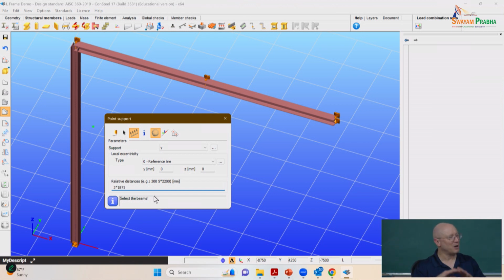Out of plane. Yeah, we've been talking about an in-plane analysis, and now I'm jumping to it being a structure, so we have to actually support it out of plane, right? We did a planar analysis, but we can look at the out of plane buckling here in a bit. You need to know how many out of plane braces you need to provide. That's right. I've already looked at the design of this column, and I need 4 braces out of plane to get it close to working. One at midpoint will not be sufficient. It won't support the load that I'm going to try to put on it.